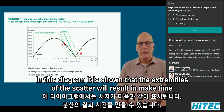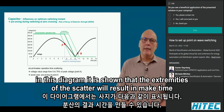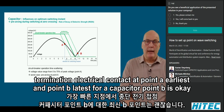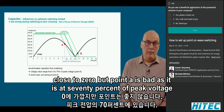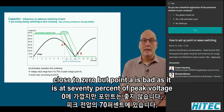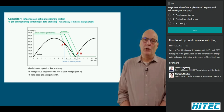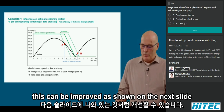In this diagram, it is shown that the extremities of the scatter will result in make time termination, electrical contact, at point A earliest and point B latest. For a capacitor, point B is okay, close to zero, but point A is bad as it is at 70% of peak voltage. This can be improved as shown on the next slide.